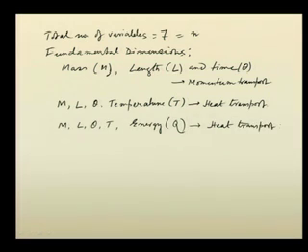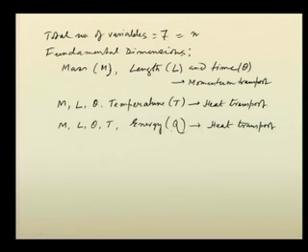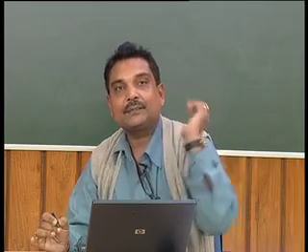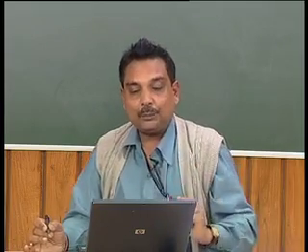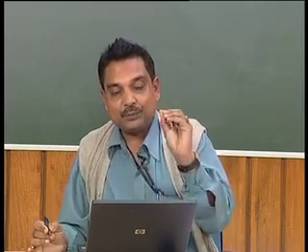But however, what we will do is, in either of the cases we can generate a similar kind of dimensionless groups. Energy is taken separately as a fundamental dimension, but energy also can be expressed in terms of m, L, theta, and T. Somebody, if interested, can put another fundamental dimension like Q. So, the fundamental dimensions in heat transfer could be 4 or 5.